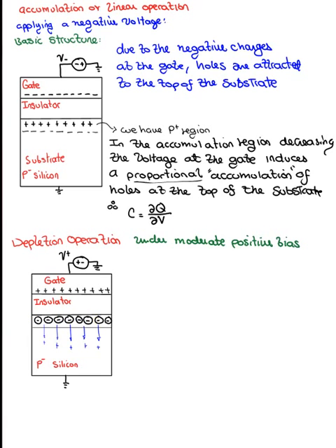But as we mentioned before for the PN junction capacitance, this capacitance as well is non-linear, because you have a limited amount of holes in the substrate. In the beginning, as you increase the voltage at the gate, some of these mobile holes are going to get out of there, and the charge is going to be proportional. But as we reach a limit, and the number of holes available in this region is very, very small, pushing that voltage even higher is not going to make much difference in the amount of charge stored. And so you have a non-linear capacitor.